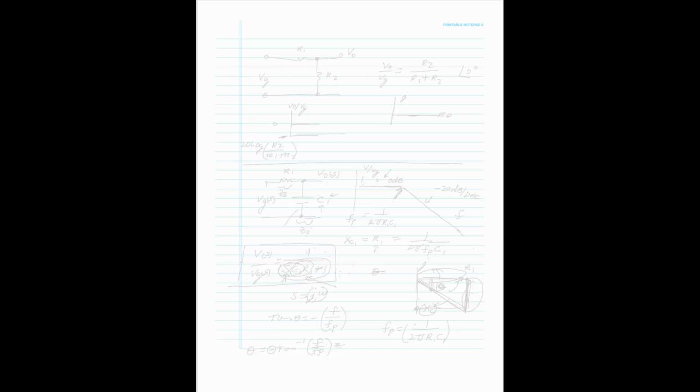You find the transfer function, you know what you want, you look at the loop, and you go step by step. And what you've got to learn is you've got to know what a zero is, what a pole is, and what a right half plane zero is, so that you are able to cancel poles and zeros to get what you want. And typically what you want in a converter is a dominant single pole roll-off. That's true a lot of times with op amps too. So that's how we have to start.